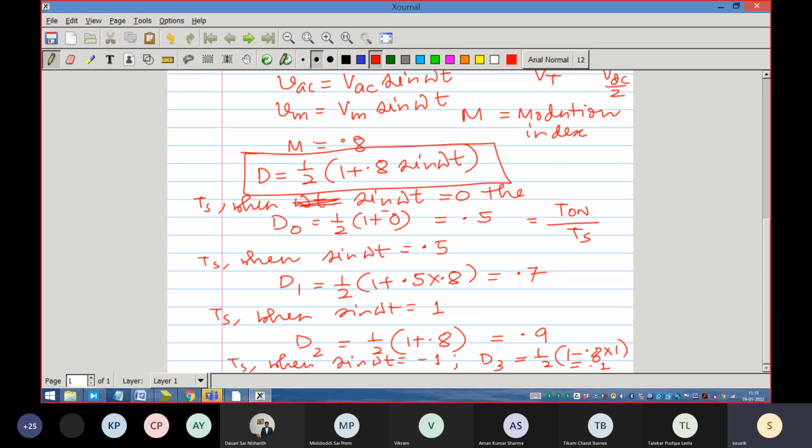But you have cleverly chosen the duty ratio, the structure and the modulation in such a way that you are producing both plus voltage and minus voltage with respect to one reference. And the reference is where? The reference is the center point of the DC bus. It is not at the end of the DC bus. Your DC bus you have split into two, and this you have taken as the reference. This is VDC by 2 and this is VDC by 2, and you are doing a switching here. You are measuring the voltage between this reference and this point. This is the AC voltage that you want to produce here. I hope this is absolutely clear. This should be clear to you.